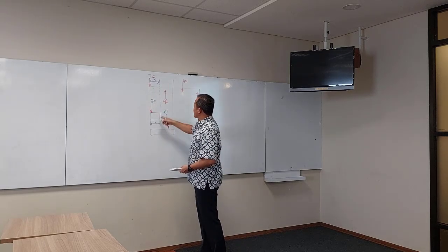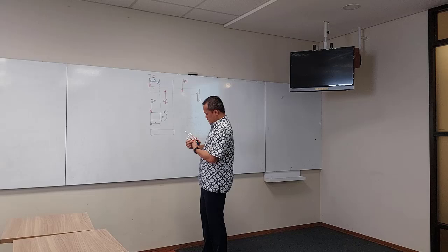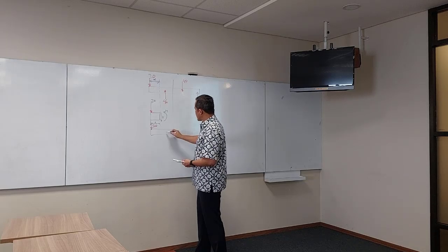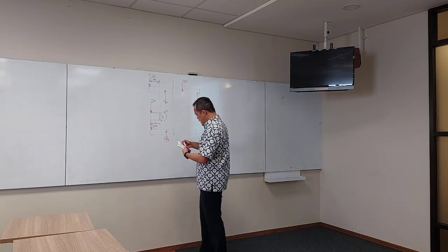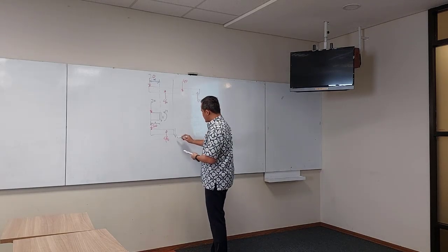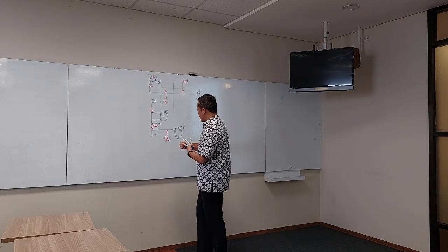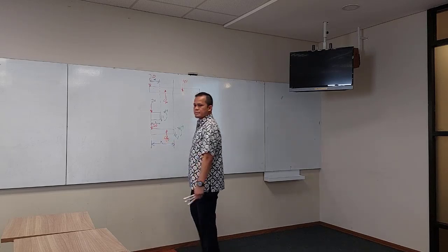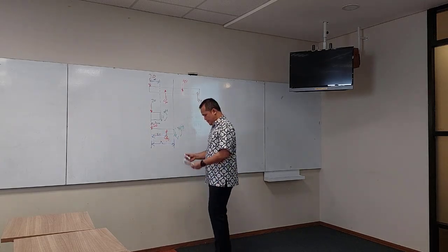In between we apply sectioning. Another between we apply sectioning because we believe there will be a changing. Right? What will you do? You know that there is a 20 kilonewton applied here. This is 20. And then 46 kilonewton. Okay. And then V is applied. M is the internal bending moment. And it has a distance of x. The distance between 20 to 46 is 2.5, yeah? Right? 2.5. Okay. Now guide me.